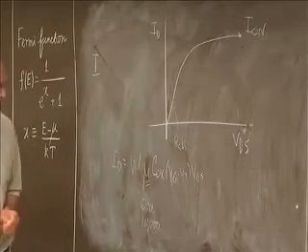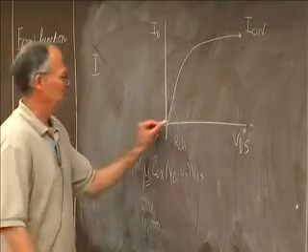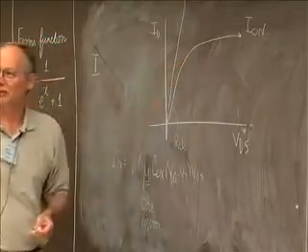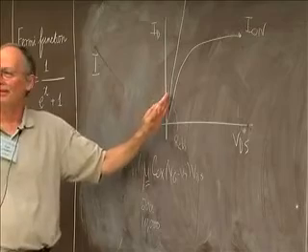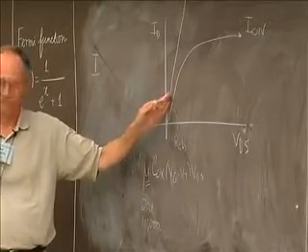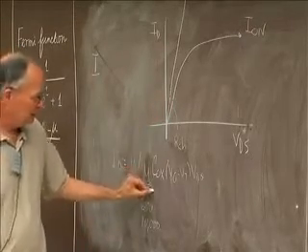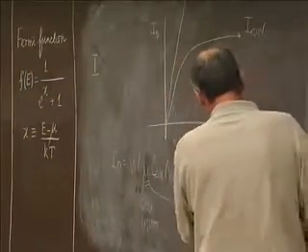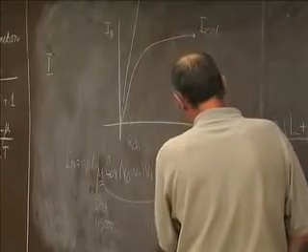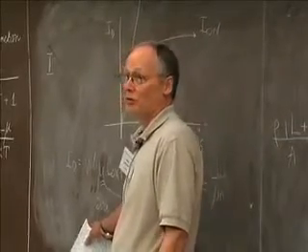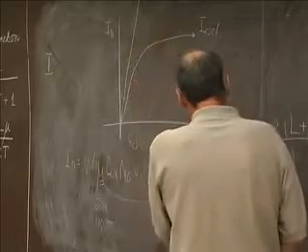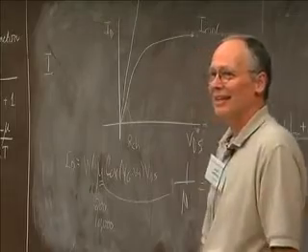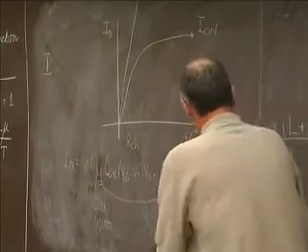All right, but it wouldn't quite work that way. I mean, that would give you more steepness, but you're going to saturate. And also, you can't get steeper than the ballistic limit. So this mobility really here, 1 over that mobility is 1 over the actual mobility, which might be enormous for these materials, plus 1 over this ballistic mobility. And that's the thing that depends on channel length.